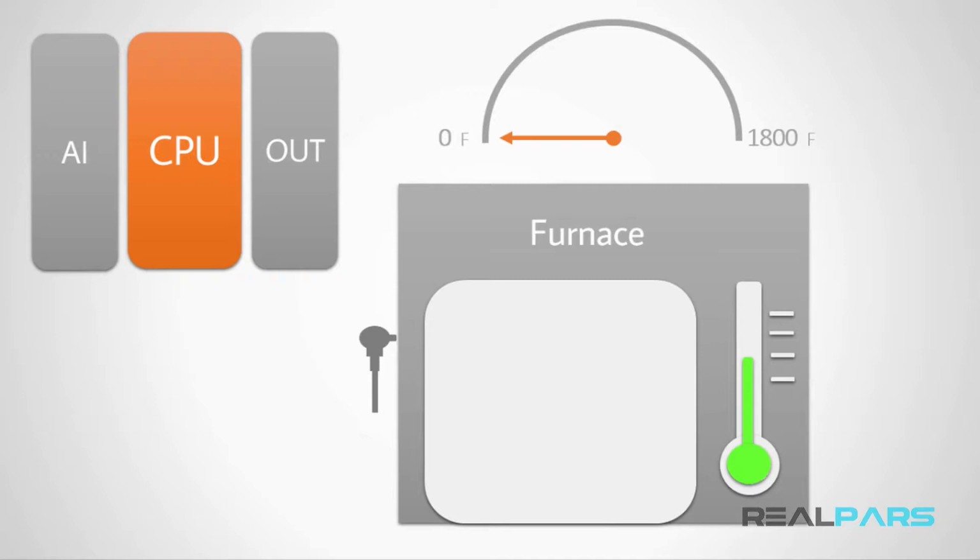it can have any value. For example, the value of this signal could be 100, 500, 1200, or any other value between 0 and 1800. Hence, we can't connect this type of signal to a digital input module, which can only receive 0 or 1. Therefore, we need to connect that to an analog module that can potentially receive an analog signal from a thermocouple.